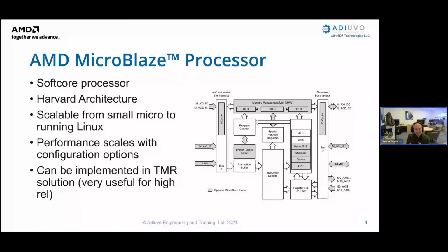Typically, Jonathan, when you create TMR solutions, they run from their own block RAM, and you would do some voting between the two. Obviously, however, it is actually possible to do that and share the application, with the application running in DDR, and share the application between the three. In that instance, it should be able to run with PetaLinux. I've never tried it actually, but I'm now writing a mental note to myself that I should put this on the list of things to try and do.